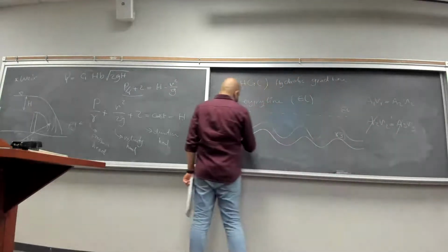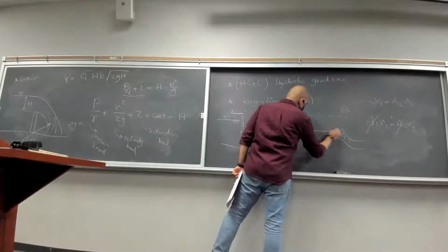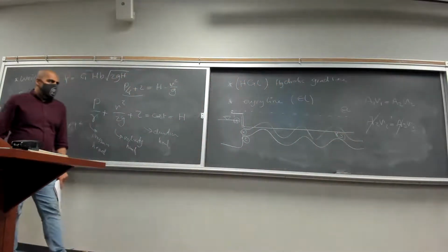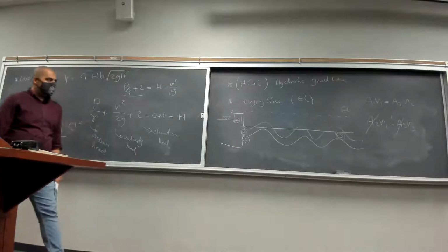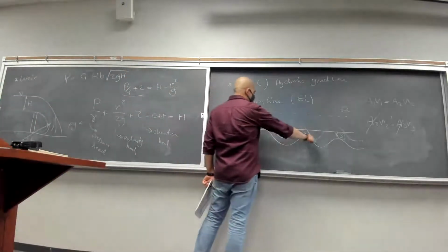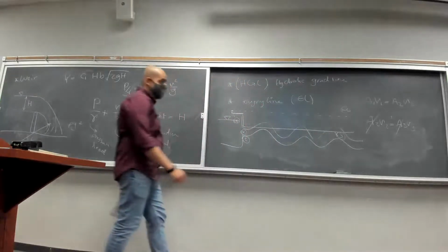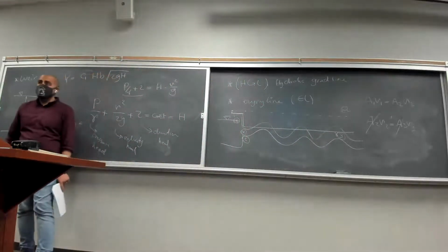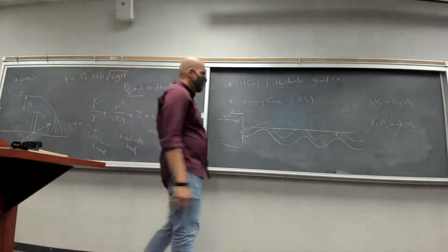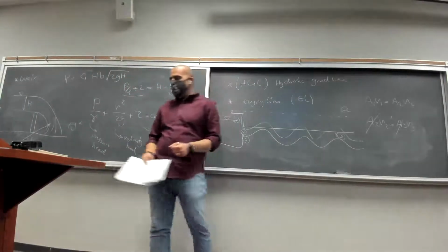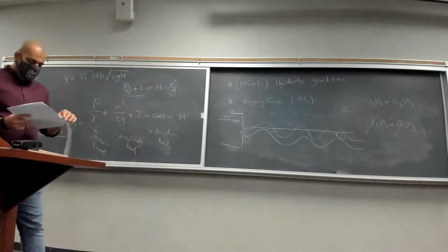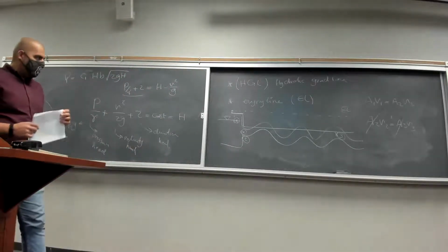So your hydraulic grade line is going to look like this for the rest of the thing, which essentially means that your pressure, and since elevation is changing, your pressure is going to change as well, and its change is going to be proportional to your elevation, right? So these are just 2 concepts that were introduced in your book, and I guess we just had to introduce them as well.